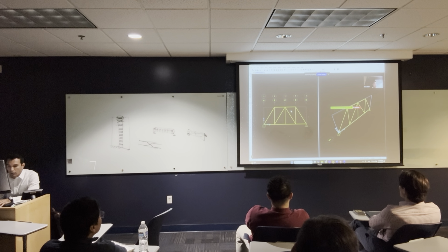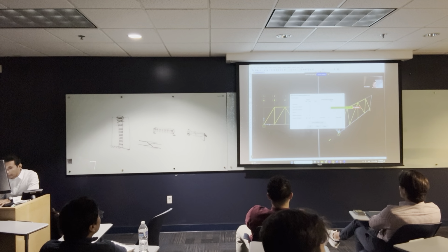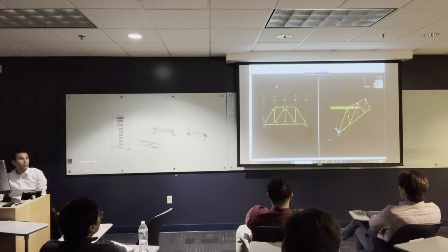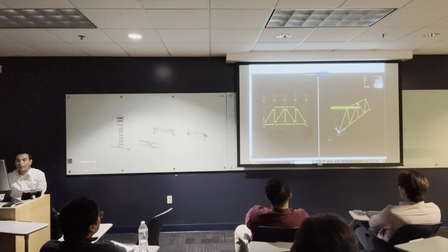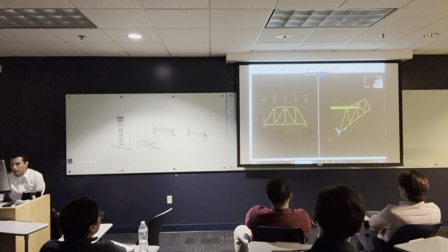I'm gonna select all of them and assign Frame, Release and Partial Fixity, and I'm gonna make all of them equal to 0. So right now, this frame is right. So let's run the analysis and see what is gonna happen. Run now.